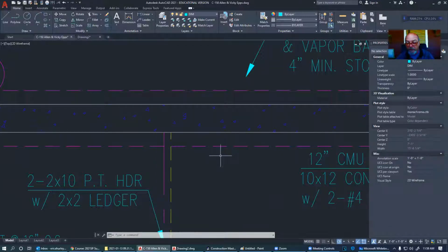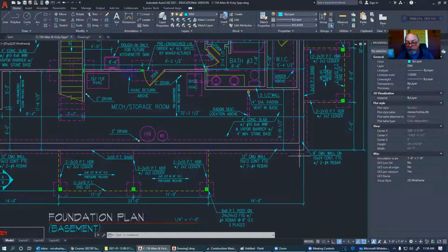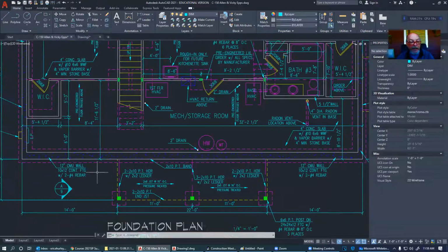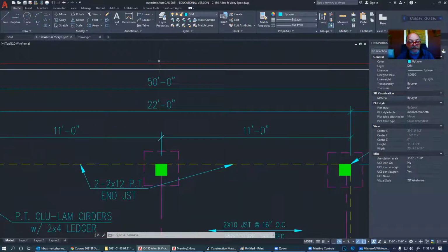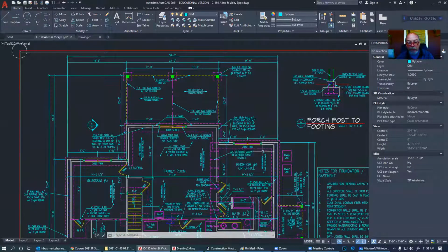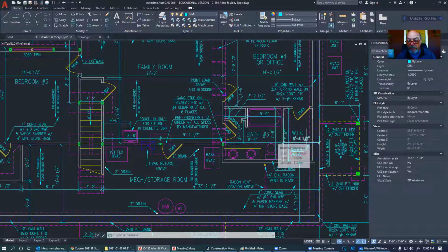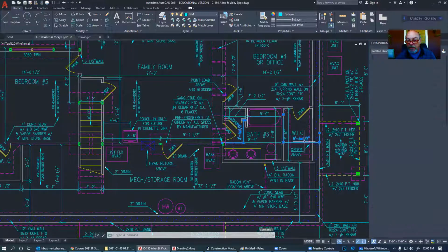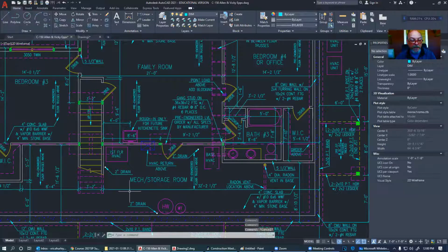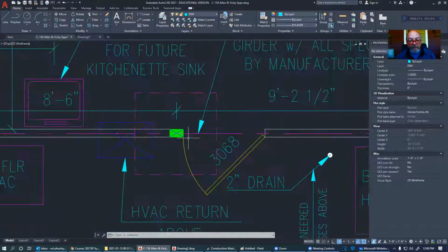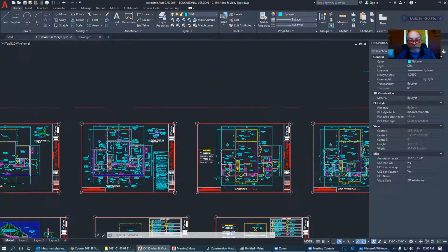All right. Some of this stuff we're not going to try to get nitpicky on, because if you'll notice, all of the dimensions come from the outside wall, and that is going to be 50 feet in this case. We're not going to lay out a wall to 49 feet, 11 and 5/8 of an inch. It ain't going to happen. When we're trying to build a house, we want to keep these numbers as simple as possible. If you'll look down through here, you will notice that the smallest increment on any of these dimensions is 1/2 inch. I don't want to give the builder any room for error. I want to keep it as clean as I can. So for instance, let's say I'm drawing this out, and let me get over to the floor plan for a minute.